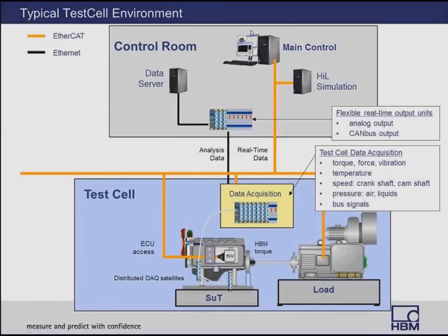You also have the actual computer, the control computer, which is running the data acquisition software, in this case D2T Morphee. And if your application requires some hardware-in-the-loop simulation, because in your dyno testing, you may have certain aspects of the application which are not developed yet, but there's a mathematical model that can work this aspect of the application.